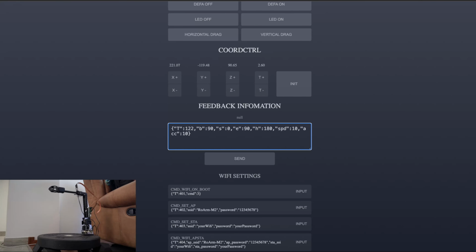So you can just change this, and once you submit, you'll see the robot arm is going to try and get to those coordinates with the speed that is set here. You can see speed 10, which is about half speed. It's moving along. So let's reset it at maximum speed, which is actually 0 in this case. You can see that's a significant speed increase. And let's change this.